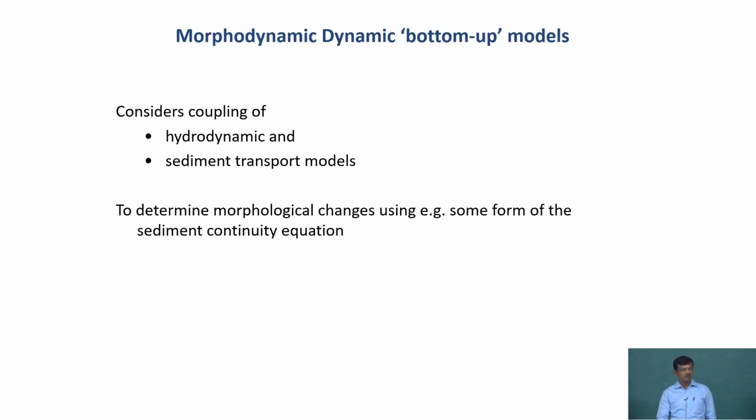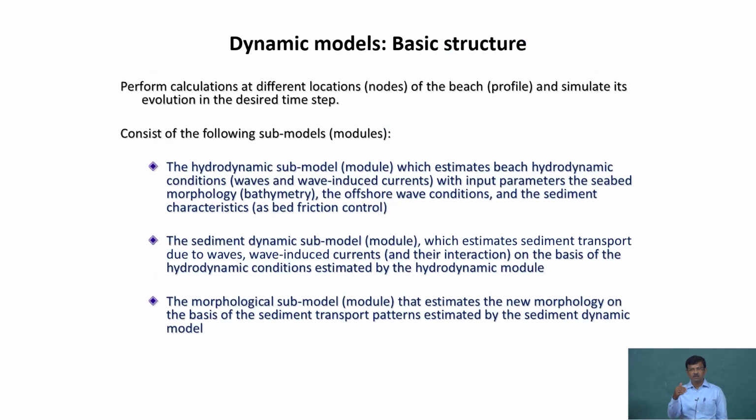And dynamic models, which are also called bottom-up models, integrate the full driving force models, short wave or long wave, with the sediment transport models, with so many sediment transport equations, integrated in very good form, linked to particle velocities, and we can drive it in 3 stages: hydrodynamic, which includes waves, long wave and short wave, then the sediment dynamic submodule, which estimates the sediment transport due to the waves and also to the current.